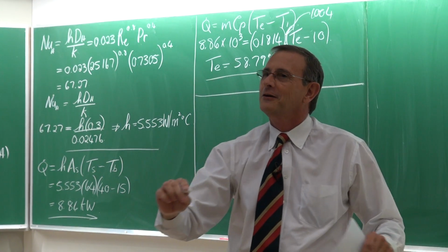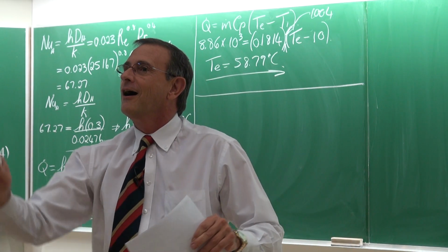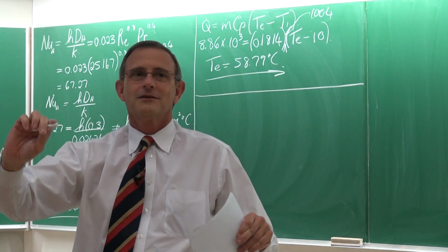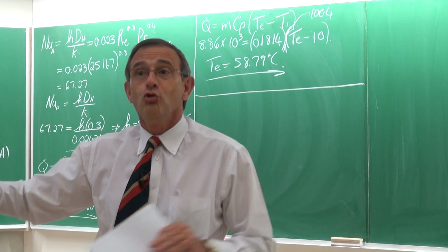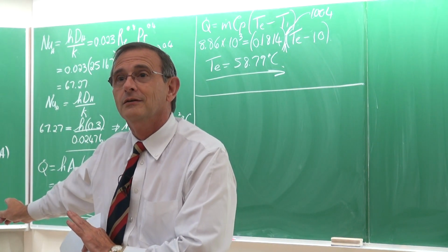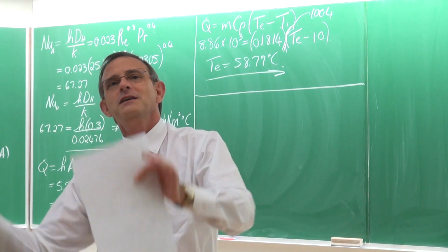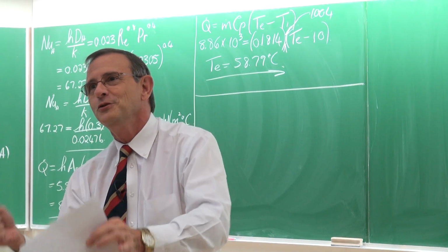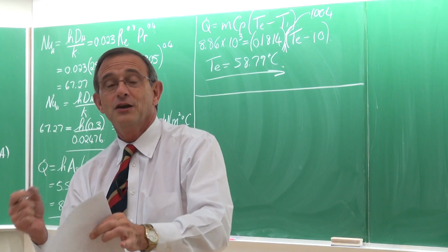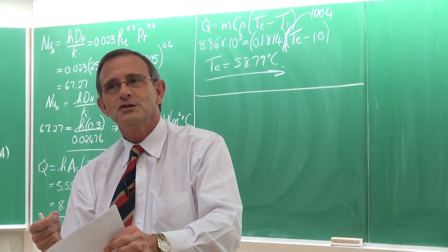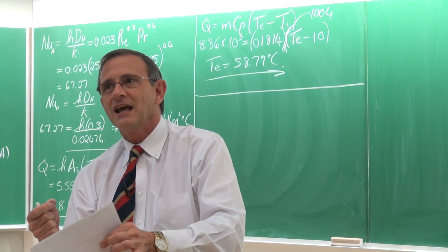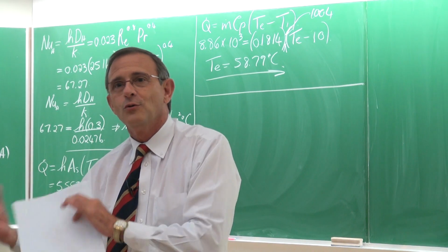You should use the law of temperature difference. Aha, yes. Thank you. It's all wrong. It's a trap. It's the classical trap. I've spent theory, and I've explained to you why it is important that you cannot do it. You've got a constant wall temperature, you need to use the LMTD. Otherwise, this is going to happen.